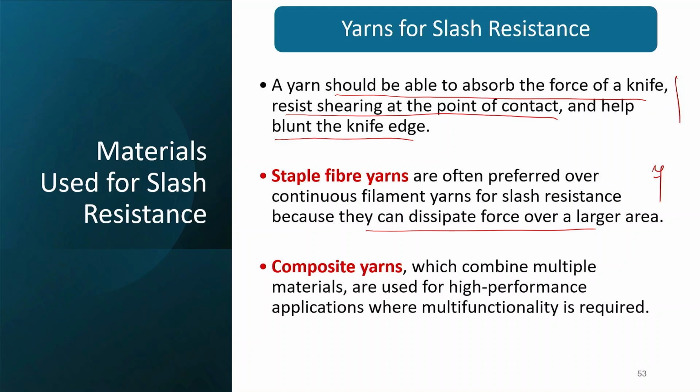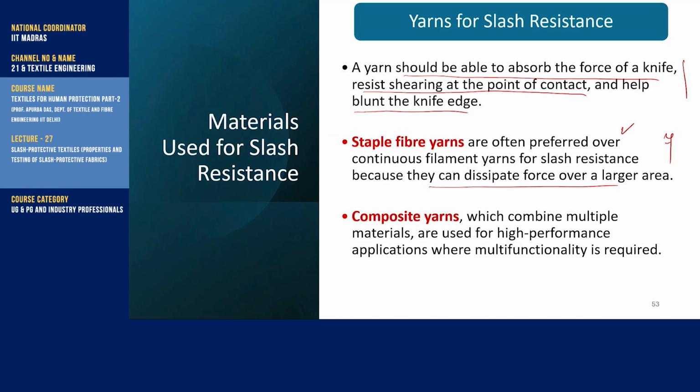and staple fiber yarns have a main drawback, which is their strength properties. Due to the twist application, the fibers share of the fiber load on the total strength characteristics is reduced as compared to the continuous filament.